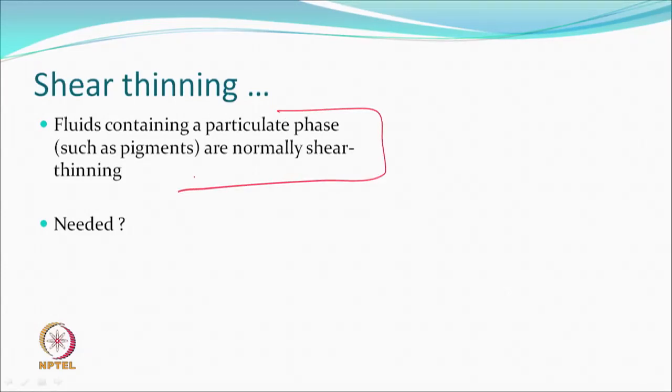Yes, we do require shear thinning, because the time taken for even the smallest droplet to come out of the nozzle is very, very small, and therefore the shear rate is very high. If it is not there, back pressure will develop, the actuators may not work very nicely, they may get affected adversely, and the functions may be badly affected. And so, we do require shear thinning behavior of the inks for printing.